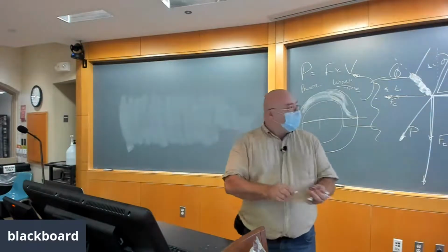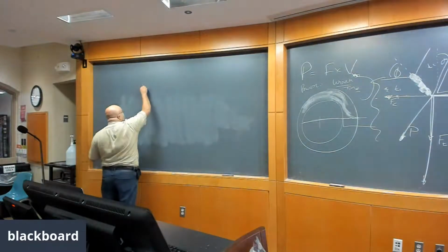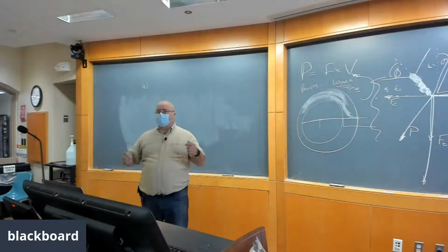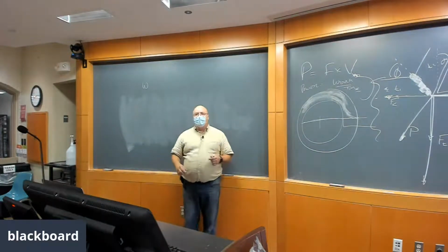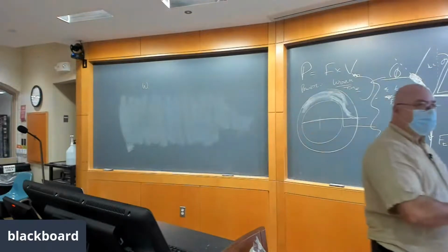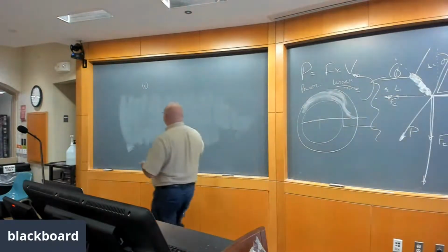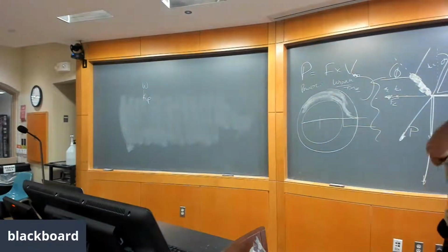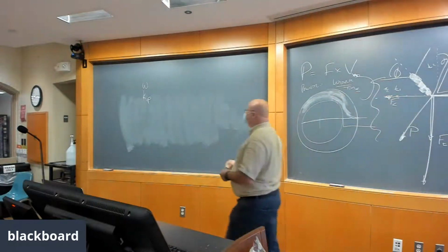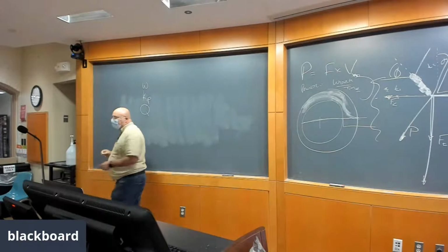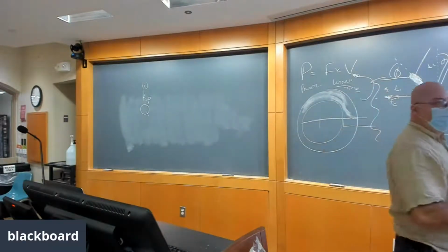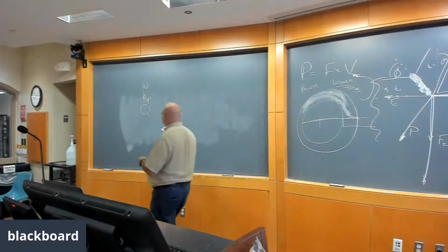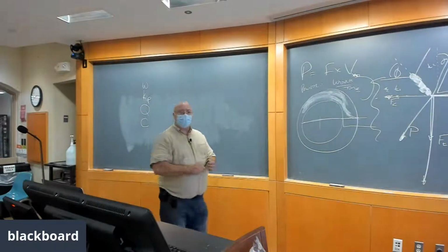Oh, okay. So the sharpness of the tool. I think we call that one W. How sharp the tool was. So the tool wear factor, that's where the W comes from. What else did we care about? The machinability of the material, the material properties. We get this KP value, and we look that up in our Machinery's Handbook. What else did we care about? Material removal rate. We call that Q. And what else do we care about? There's this feed factor. We call that C.